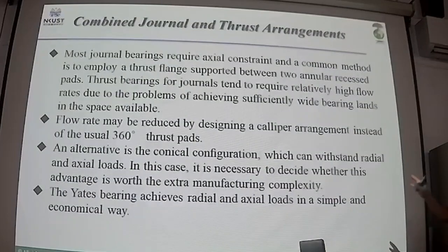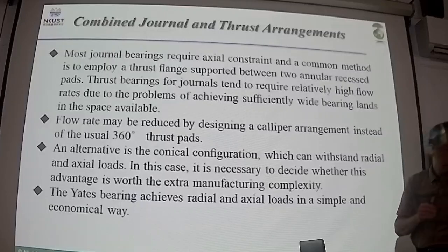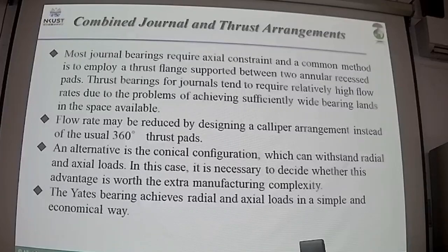To understand the basic configuration of the thrust bearing and journal bearing, it's necessary to understand how you can design a spindle, for example, a milling spindle or grinding spindle. For those kinds of spindles, you need to have combined axial force and also radial force resistance.